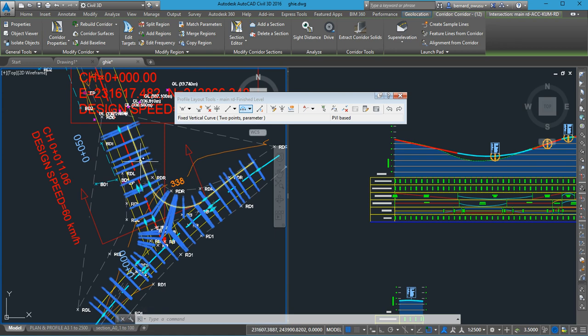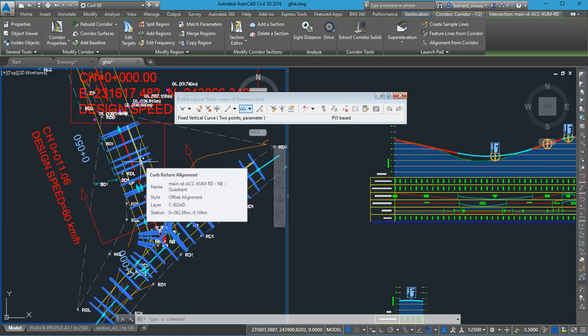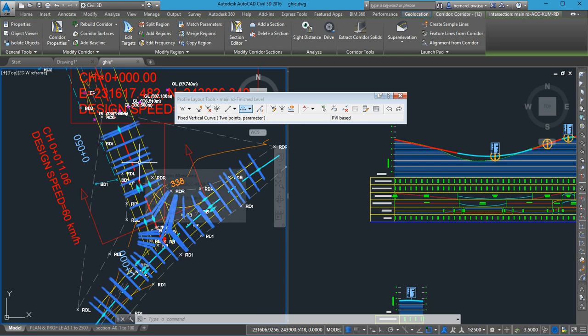Then it means that when you were inserting, where it says create intersection, you turned it off. And those who don't have it, you turned it off. So I want you to undo and start the intersection again. And when you get to the last step where it says create intersection with corridor, make sure that it is checked. Yes. We passed that. In it, you have to specify.